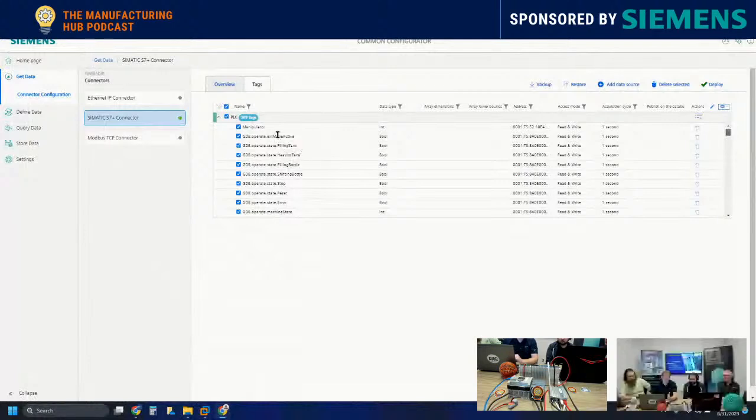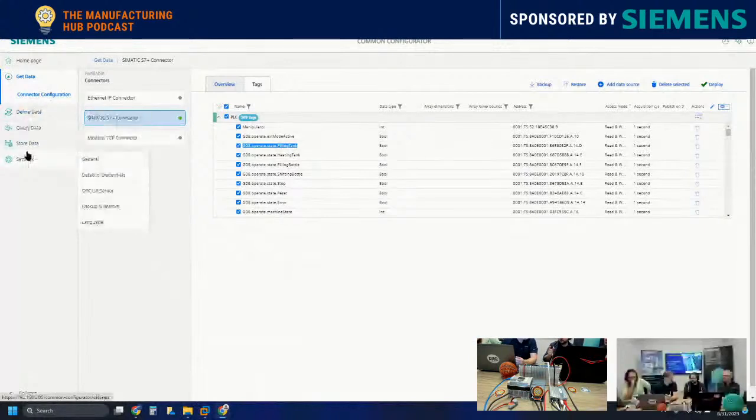So very rarely in the real world have I run into a PLC program that has my data blocks named very well, and to be able to drill into it later and understand what that tag is and everything else. Oftentimes you end up looking at more of an address space, depending on the brand of PLC that you're looking at. So you don't necessarily know what that value is unless you're the guy who programmed it. Oh, so you can remap it also? So you can rename and reshuffle the data, the tags?